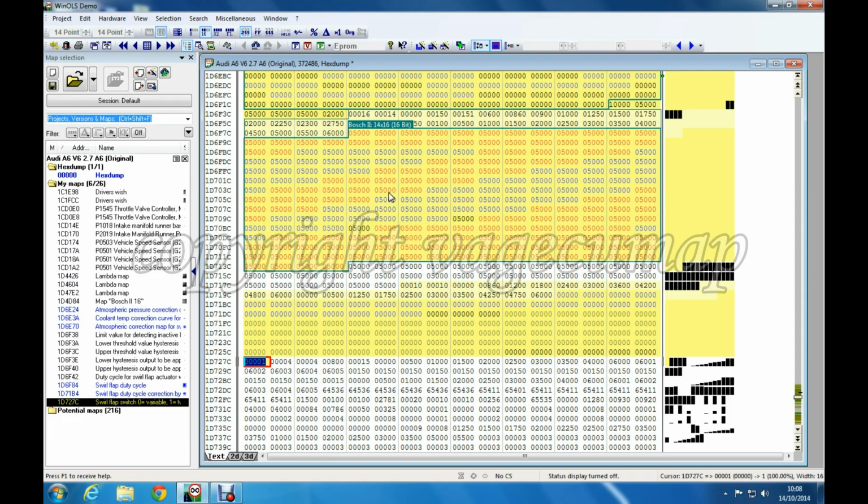I'm assuming that's either on or off, and what they mean by that is that the throttle flap is still working, so the air intake is either open or it's not. So I'm assuming that that's what they mean. Now I'm assuming then that the system defaults to these values here, which is why these values are found on engine ECUs that don't have the flaps enabled, and this is often set to 1 on those as well. So again, it helps show that that's the value for not enabling the swirl flaps. So we have a sort of double approach here.